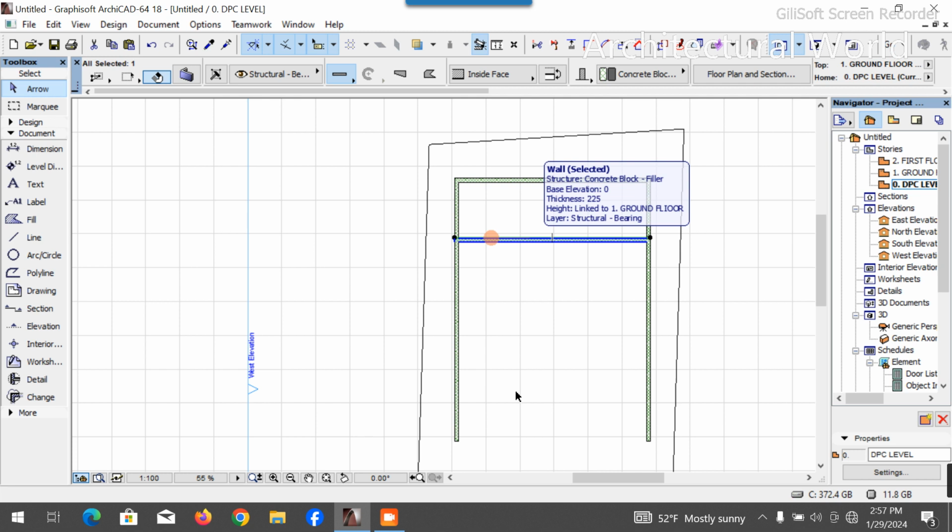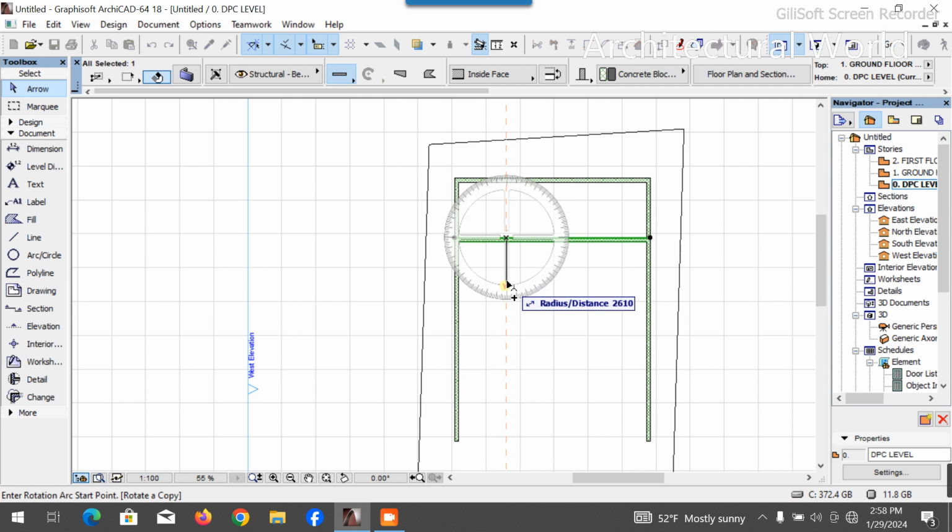Now I need a toilet. I want to show you how to form a plan. You can't just form everything together. First, look for one particular thing. Now I need a toilet to serve this room. So I'm going to copy this wall, because this is the maid room. I'm going to give him or her a toilet of 1.2 meters, or let's say 1.3 meters. If I add my block wall to it, it's going to give me 1525 millimeters.